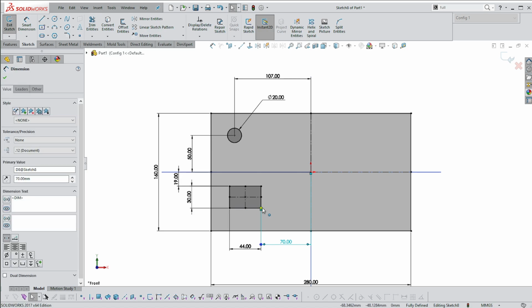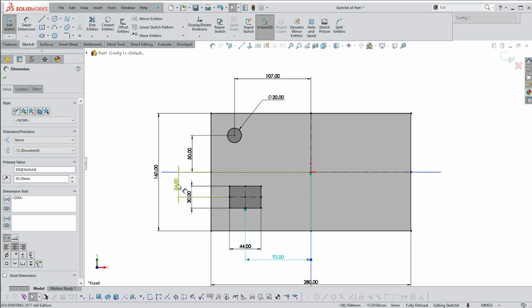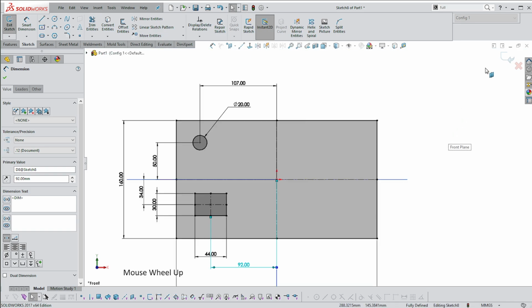What I can also do is, depending on what's important to me, on what my design intent is, make these center lines the position dimensions. So what I'm doing here is grabbing that end and locating it. That could be important because maybe there's a reciprocal part on another block of wood that has to fit inside here. So I can limit the areas that I'm going to make by making those center lines the size positions. You'll see how that works in a moment.